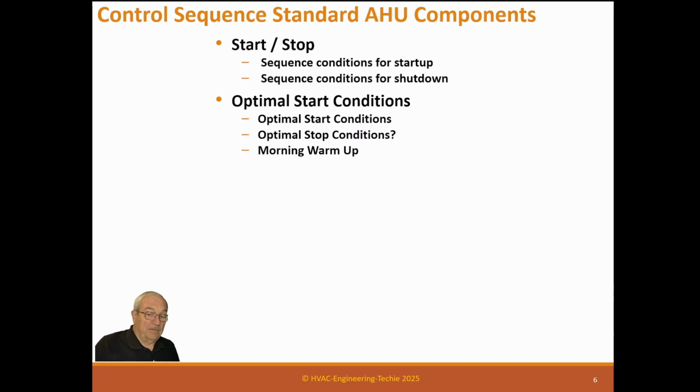Morning warm-up. Do we need a morning warm-up? Do we need a morning cool-down? Do we need to have specific sequences? Now, optimal start will actually do the same thing, right? But if it turns out that optimal start takes an hour and a half to get there, maybe you want to get there sooner. So you could do that by using a morning warm-up and a morning cool-down, which have special sequences to do that.